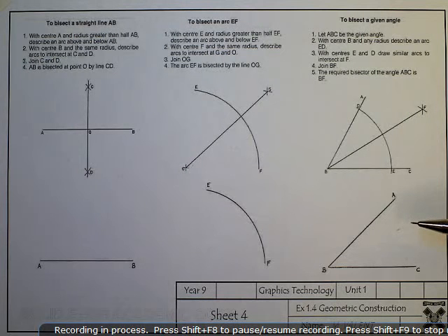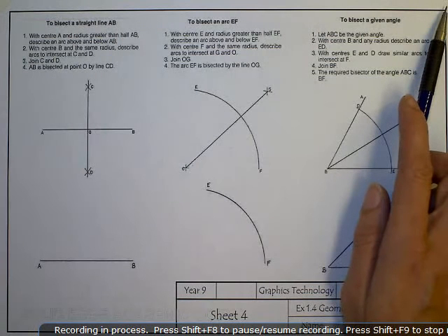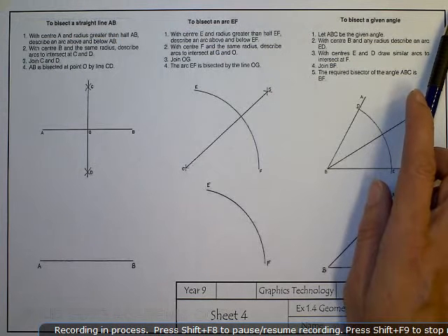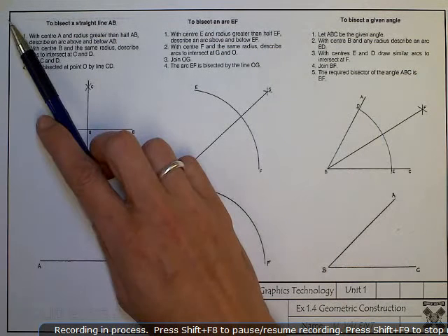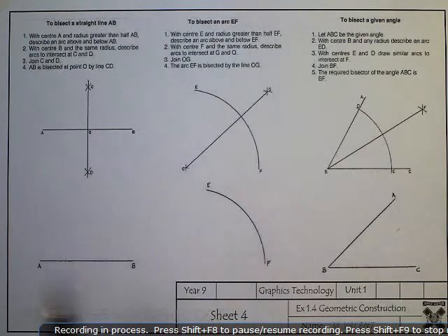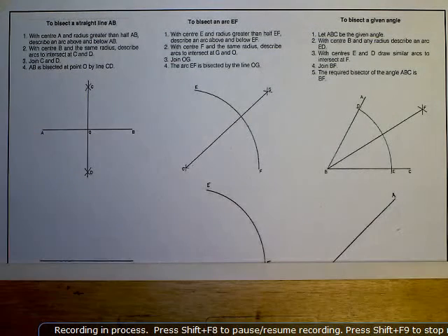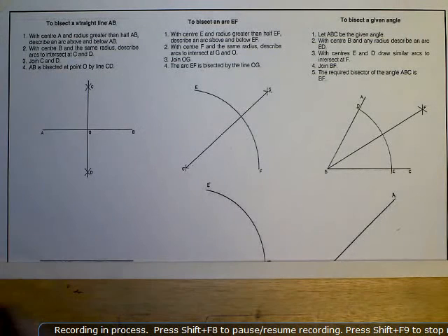I've set the page up with a small piece of tape in the top corners, just on the edge of my page. Not a huge amount of tape and not on a lot of the paper, so I'm going to find it very easy to take that tape off without ripping the paper itself, and I'll keep my drawing in good condition. Also, before taping it down, I've lined it up with any existing drawing that might be on the page already.